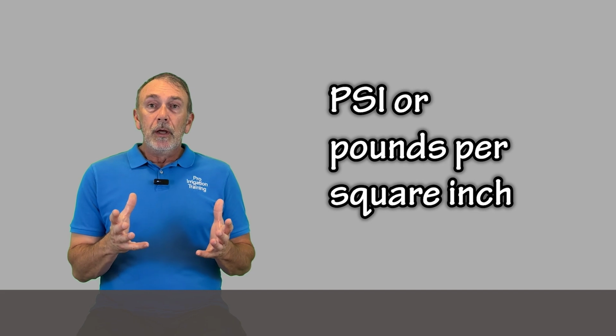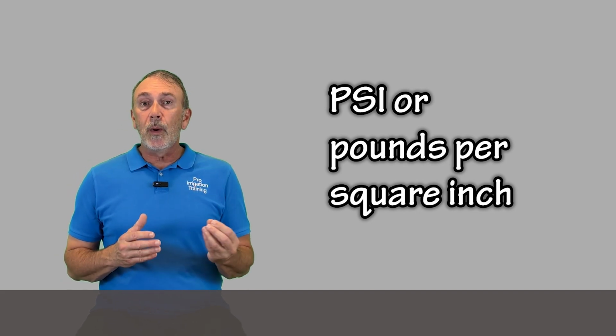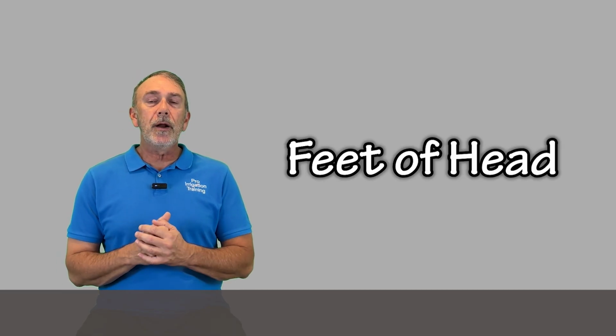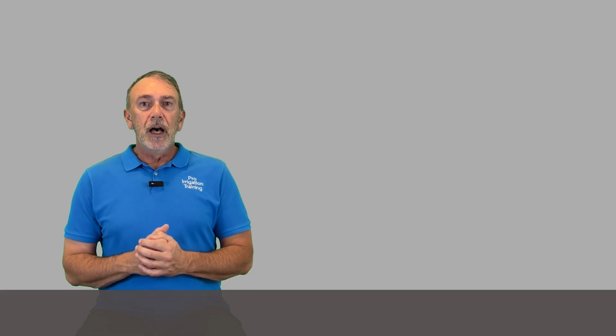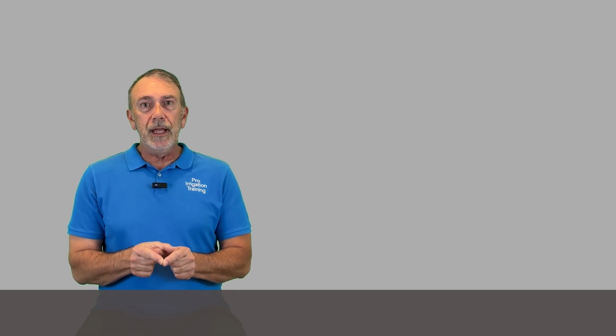And now we have two different ways of measuring pressure. The first is PSI, which stands for pounds per square inch, and then you have feet of head. Let's talk about PSI. PSI, pounds per square inch, is the measurement of a single column of water, right? A straight up and down vertical column of water that rests on 1 square inch.